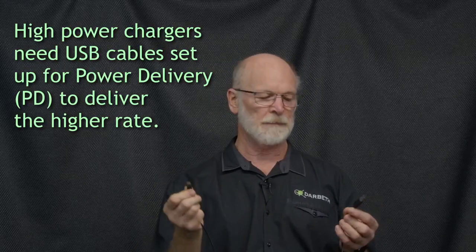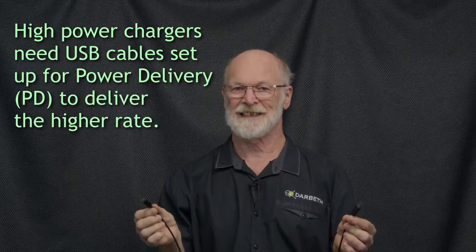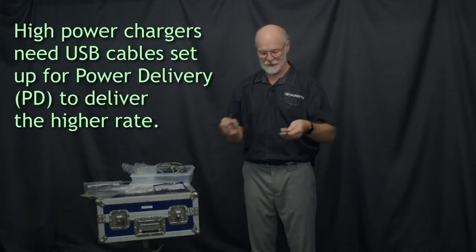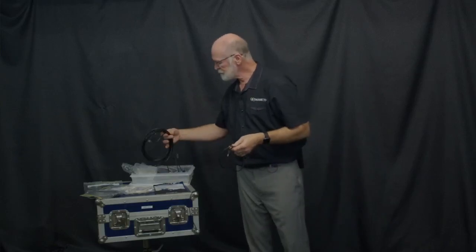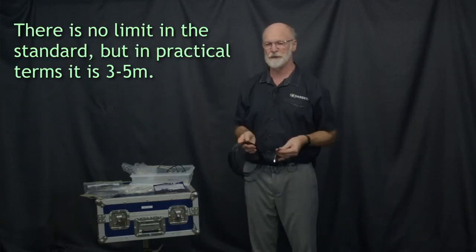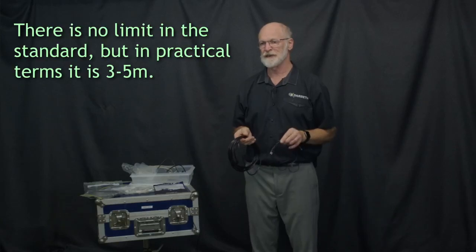And that also explains why some cables charge faster than others. So not every cable is able to charge at the rate of the charger that you have. So that's one thing to be aware of. The cables themselves have got different size wires on them. You can see that one is relatively thin. This one is relatively thick, heavier duty, and this one will go further distances, but in reality you can't get USB cables going more than 3 to 5 meters. So if you're looking for a really long run with USB, it's not on. You have to find some other mechanism to do that.